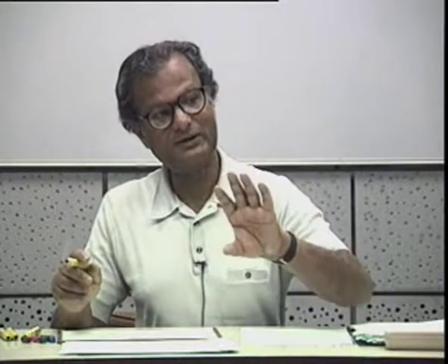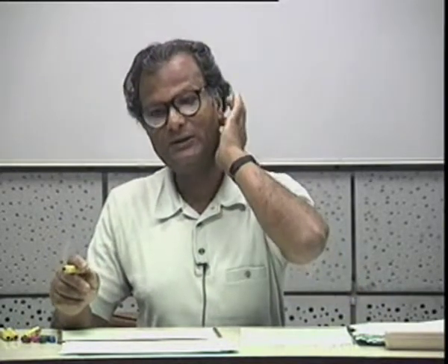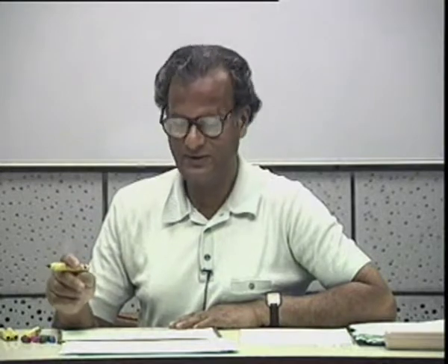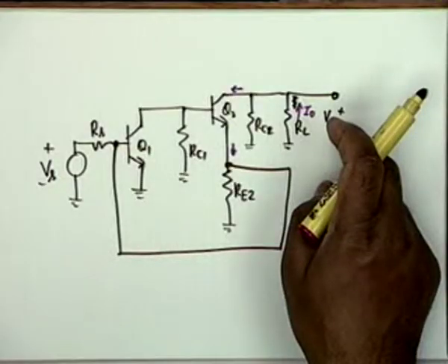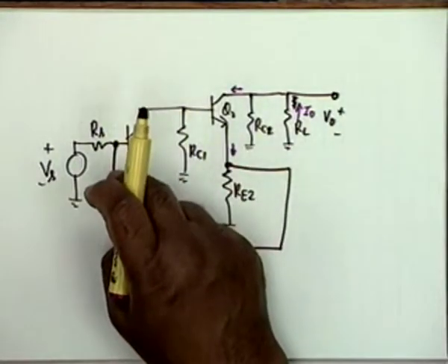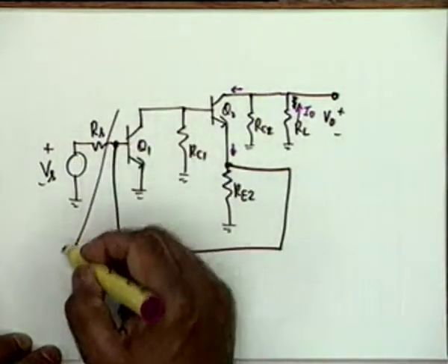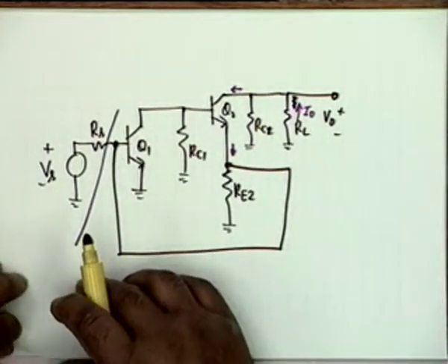Before you apply those formulas, you must determine what kind of transfer. What is the appropriate transfer function? Current to current or voltage to current? Current to current, because there is a shunt here, and therefore first thing you should do is to convert this into its Norton equivalent.